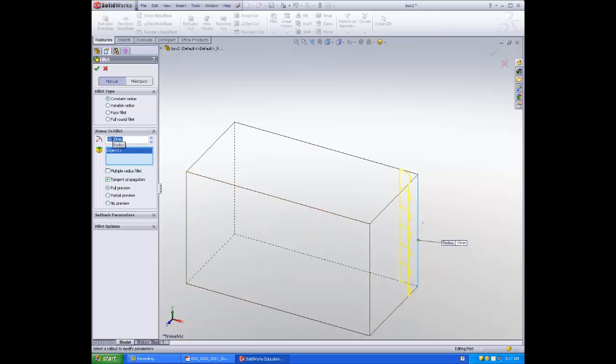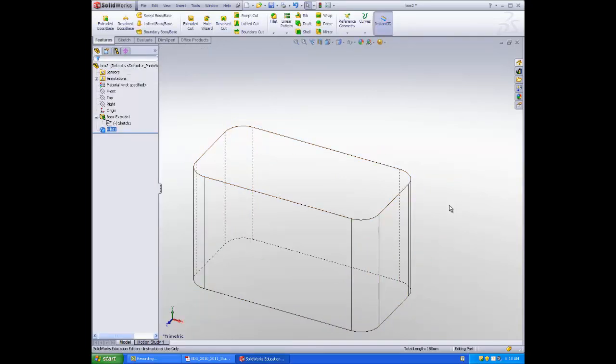I can also enter that number over here and change this number, but this is exactly what I want it to be for this particular tutorial. So if I go around and click on all these, you will see that I'm getting a radius of 10 for each of them, and now I could just hit OK, and that rounds all our edges off. Gives us a good view there. And now they ask us that we did this to go to our shaded view, which looks like this.